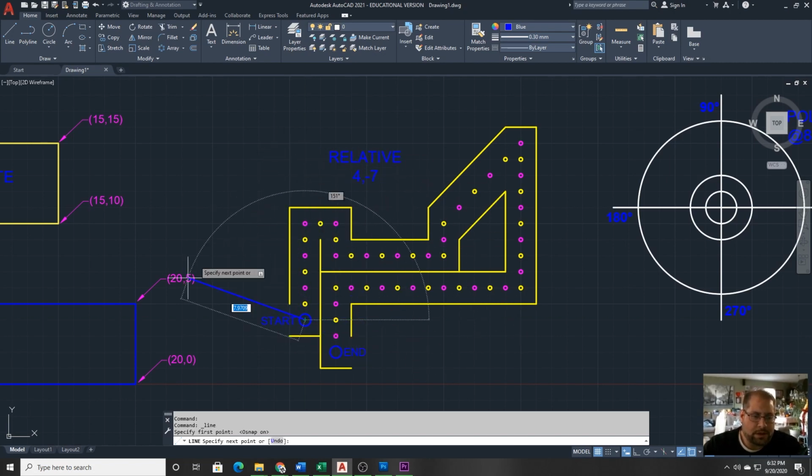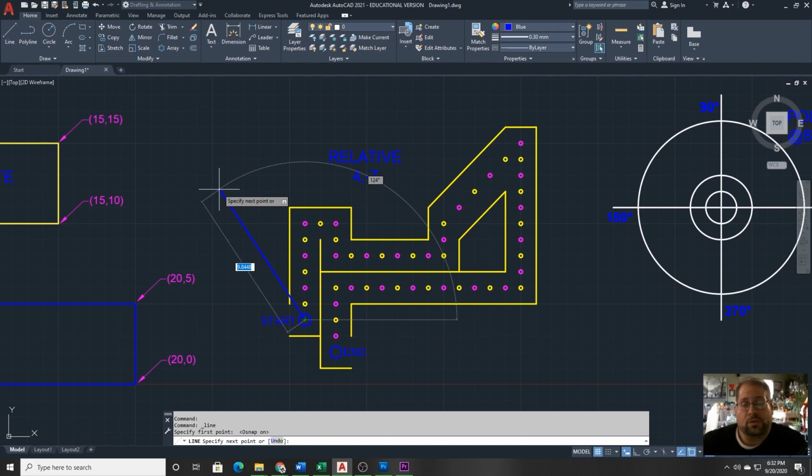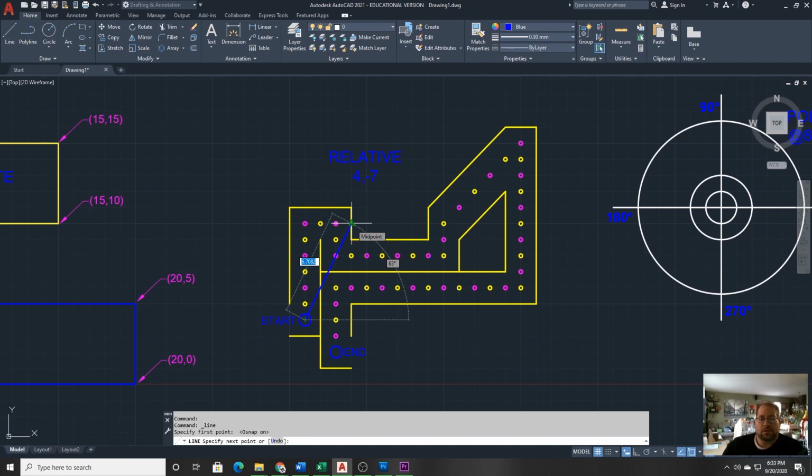So now I've started my line, and with the way the relative coordinate system works is that every time you draw something new, the origin from where you're drawing happens to be your current position. So you're going relative from your current position, moving on into other places of the drawing. Now you're going to use the X and Y axes as sort of directions to work with. The x-axis in the positive direction will be the first number you type if you want to move to the right. You're going to use a negative value for the x entry if you want to move to the left.